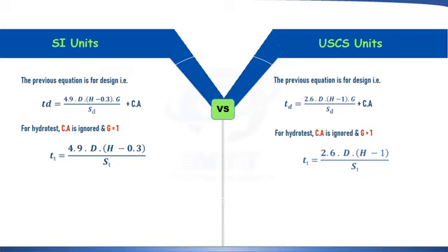Now one thing to note from this equation is that there is no internal pressure or P term in both these design and test condition equations in both units. If we compare it with other codes, like the BS standard, in their thickness calculation there is a term P, or internal pressure above the column head, in the equation. But API 650 ignores it due to its very small value in comparison with static head. Hence, we don't see a pressure P term in the API 650 equation in comparison to the BS standard.